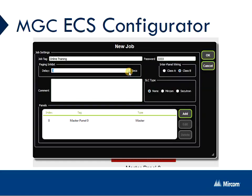You also have the ability to choose whether the inter-panel wiring is wired in Class A or Class B. This is for the RS-485 wiring between the master and booster panels. You can add comments to the job file. Some people like to add the date, or note any changes that have been made to the job if it has already been sent to the panel. In the new job window, you also have the ability to choose if you are going to use the SLC connection or not. Once you are done with this selection, you can click on the OK button located at the top right of the new job window.